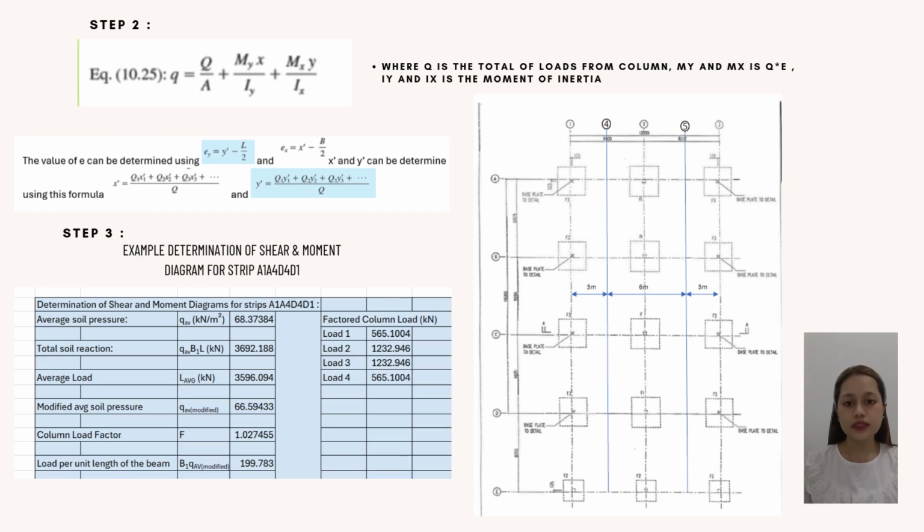So the first step to start the design calculation is to identify the length and width of the multi-purpose hall to know the area of the project. In these slides, we can see that the soil pressure is to be calculated at each column point, in this case points A1, A2, A3, B1, B2, B3, C1, C2, C3, and D1, D2, and D3.